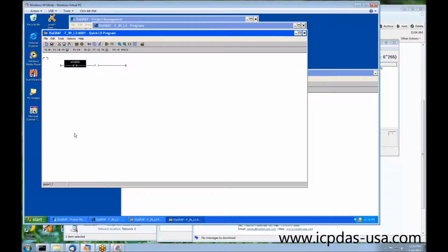By pressing the spacebar, we get this backslash, and that means not. So if we're not enabled, then we want to just jump out or return, exit the whole function block without doing anything. So we can add this return value there. So if we're not enabled with this variable, we're going to return.